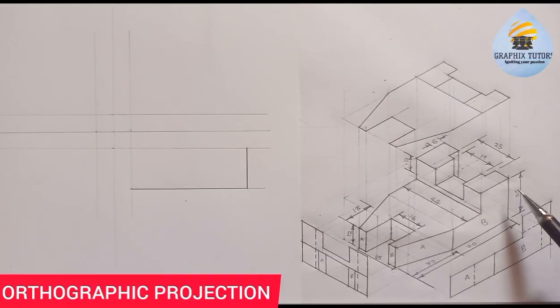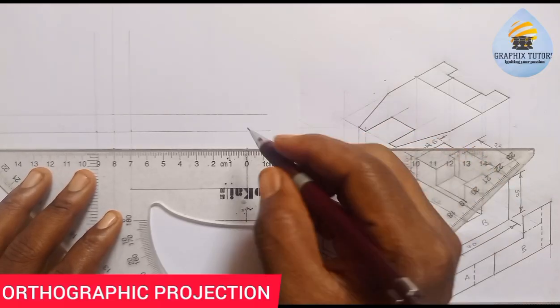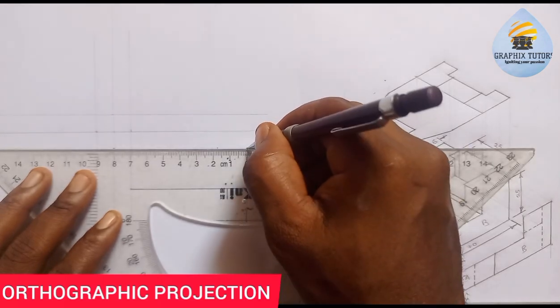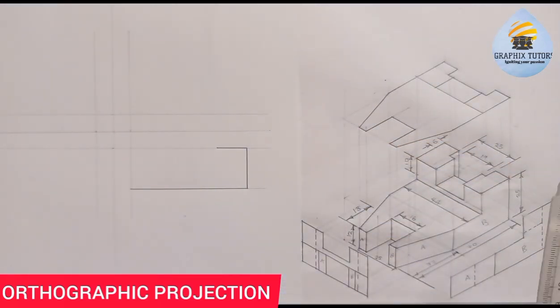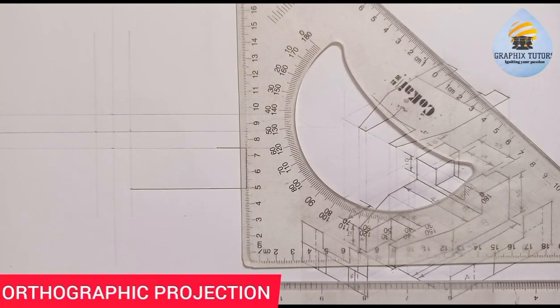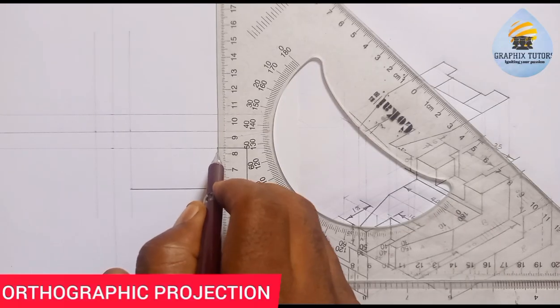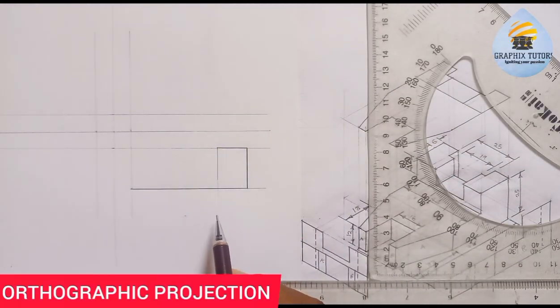in our question. So I'm going to measure 18 from this point. So 0 to 18 here. Can you see that? And I'll just thicken it once and for all. Then I'll use my faint line and I'll bring it down. Remember, I'm placing my set square on this point here. So I'll bring it down this way. So this is the faint line we have here.